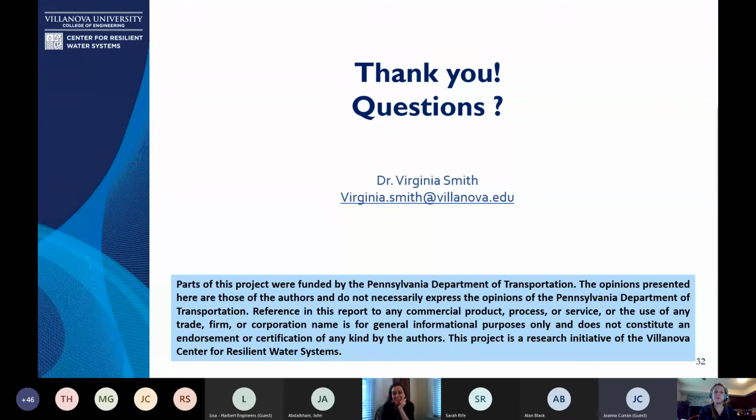Oh, I'm so interested in this, and I would love to get that data, but it's hard to come by. Getting the full sediment load, both what's moving along the bed, that coarser portion, and the suspended portion, is really challenging to do. And it's the full portion of the sediment load that's going to tell you if something's clogging or not, right? So I reported the D50 because that's what we can get, but it's the entire particle size distribution curve that actually is going to control whether or not something's clogging.